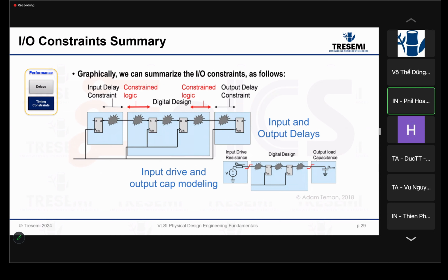And then in addition, you need to model your board level, say your input. Your input has an arrival time, and when you model the input, the best way is to use a gate to model it, making sure your driver has a resistance and a drive capability, so that it models exactly the rising and falling time on your input. And on your output, your board will have different output loads. You do this in your constraint files.